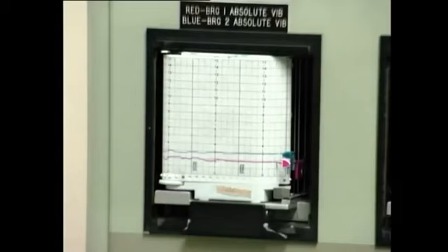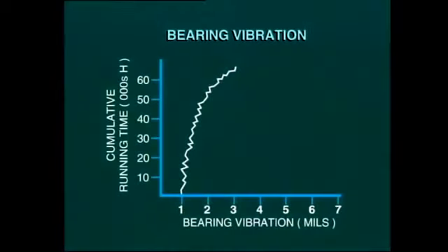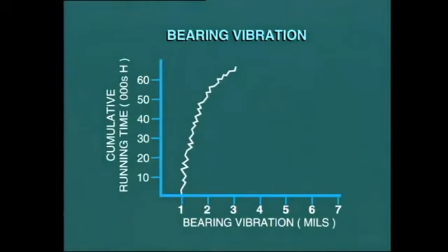If the magnitude of vibration on all turbine bearings steadily increases with time, it is probably an indication of wear and tear on mechanical components as the machine approaches the next overhaul period, usually every 5 years.